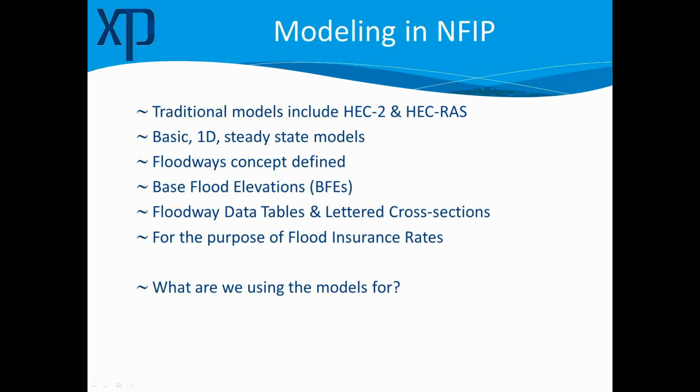That base flood was the 1% annual chance event in most cases, and again, notwithstanding coastal situations where we have V zones, but some of these were basic elements of what went into the National Flood Insurance Program, the legacy that we have. Floodway data tables and lettered cross-sections, a lot of the review criteria and conditions revolve